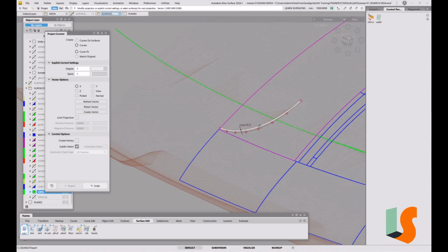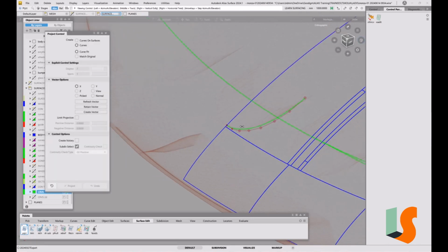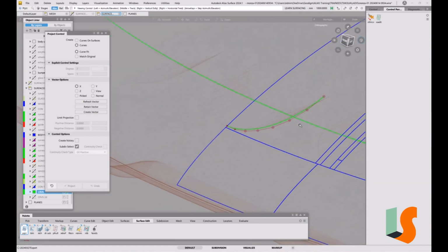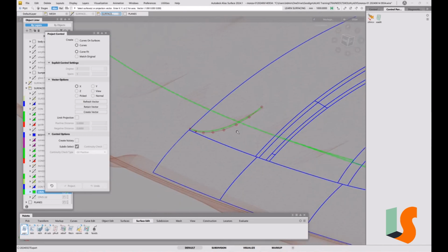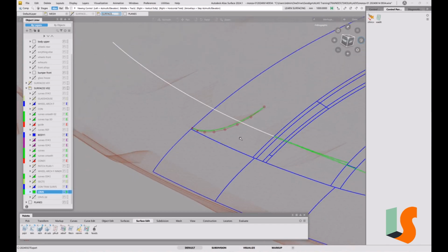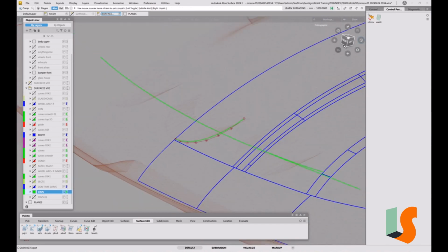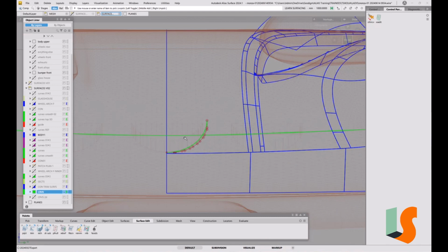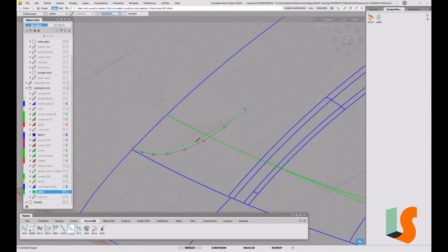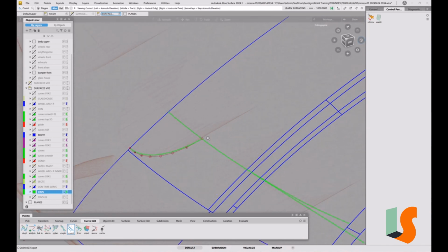When you do it off a curve on surface, you might find that you end up with a more complicated result. Obviously, we do need curves on surface at some point because we've got to trim this out eventually. But now this curve here that goes across there, we don't need to keep that all the way across. We just need the half curve there. So let me just trim that back. And this one we can trim to there just to make it easier to see.